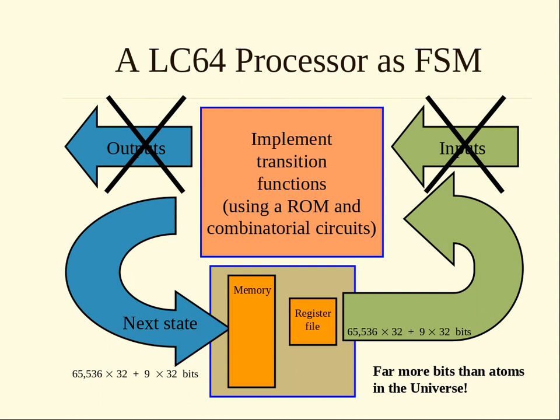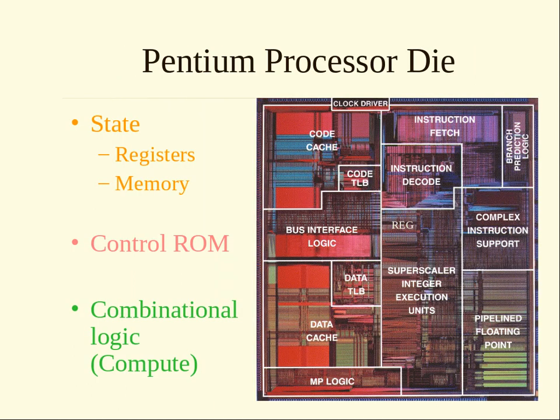Because the other thing I forgot to mention is that in our processor, like most modern processors, you have your piece of memory and you have your register file. Memory you should be used to because it's RAM. Your register file, think of it as a very small scratch pad memory inside your processor to do quick little tasks. It's called a register file because we've seen a register, which is either an SR latch or a D flip-flop. A D flip-flop is a 1-bit register. Your register file is going to have multiple D flip-flop entries so you can reference different registers.